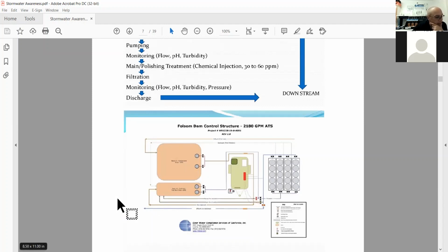It is used when traditional BMPs may not control the accelerated release of sediment from erosion caused during rain events. Used where highly erosive soils are present, long steep slopes, clay and colloidal clays are present, or very, very large sites where the sheer volume of water is something BMPs are not going to handle.